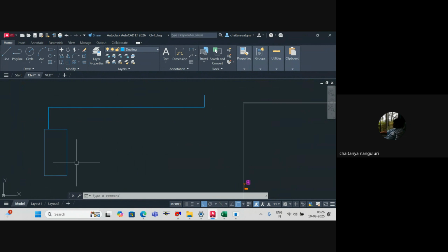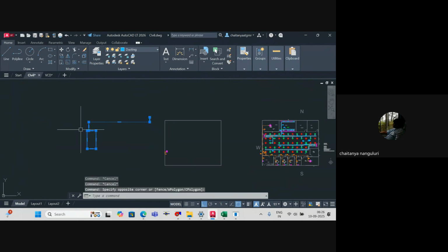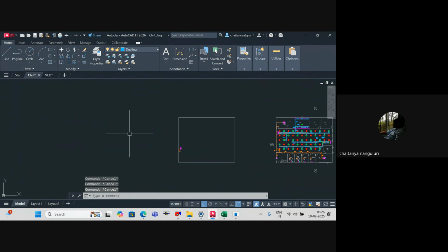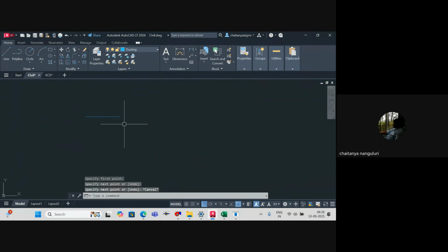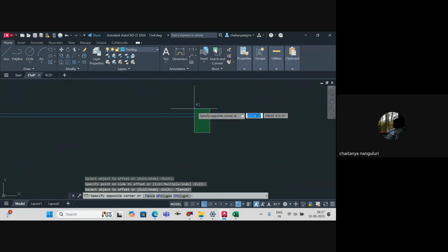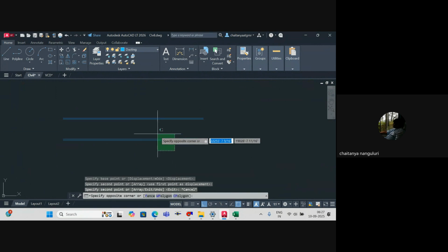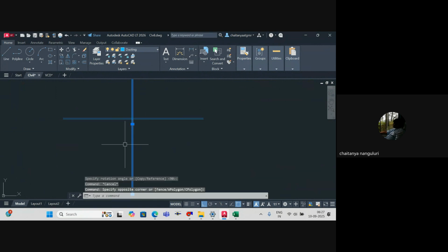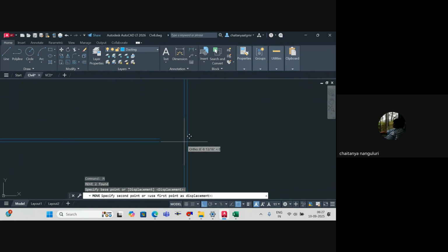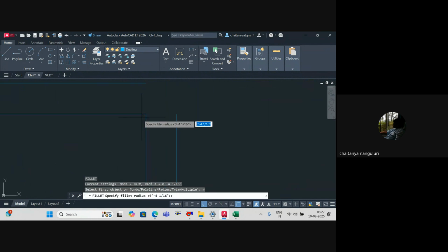So to avoid that, more than the static pressure of the fan, you will have something called a U-trap in the drain. In the elevation view, your drain will be provided like this. Let's say the diameter of the pipe is 32 mm, offset 1.5 inches. So what we do is provide elbows something like this, whatever PVC manufacturers provide, the same elbow.